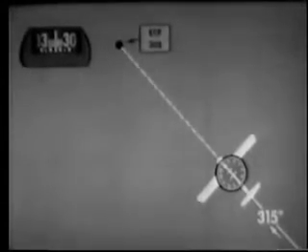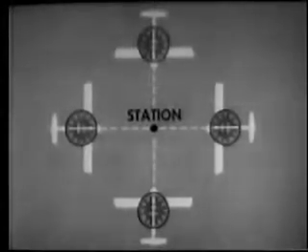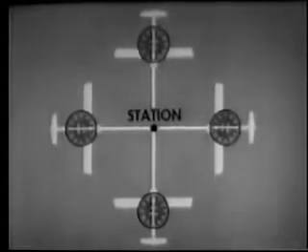A track is a straight line going toward or away from a station. Now we turn left to a heading of west. Remember, in using the ADF, don't confuse the ADF with your heading indicator. Regardless of where you are, north, east, south, or west of the station, if the ADF needle is straight up, you are headed toward the station.